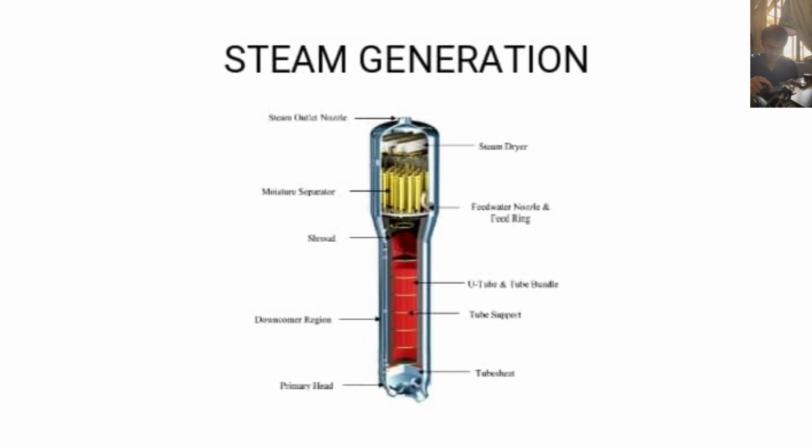This can be either adjusted by open loop control according to the pump throughput or by a closed loop control to maintain the measured temperature.